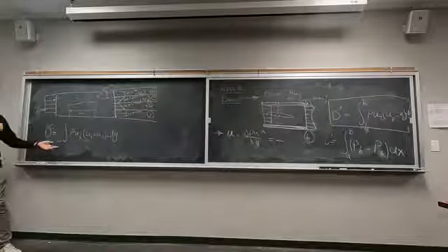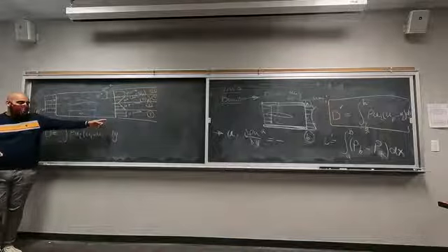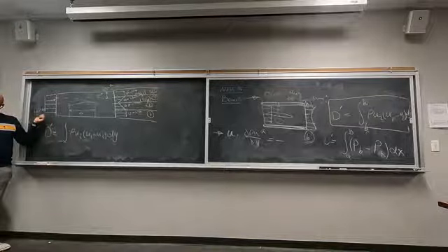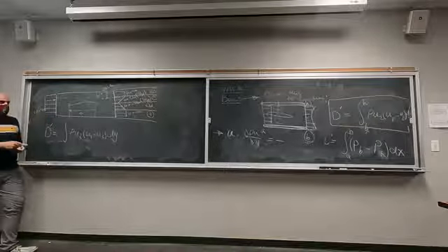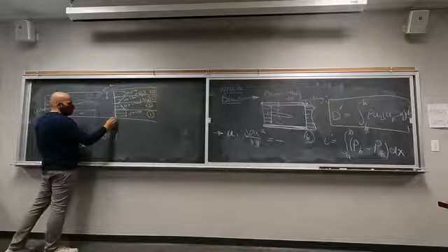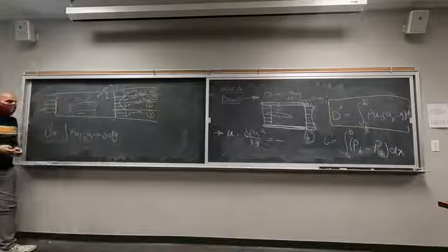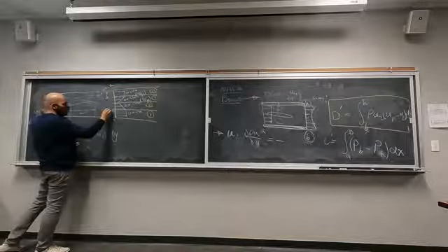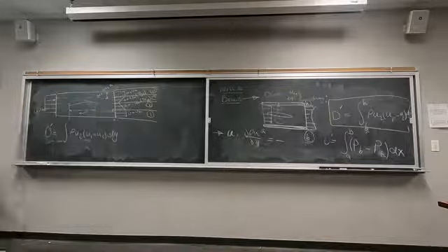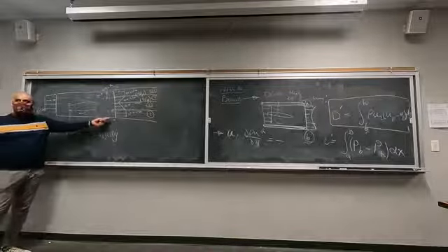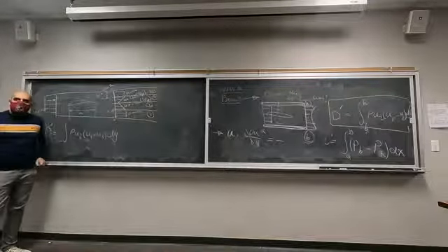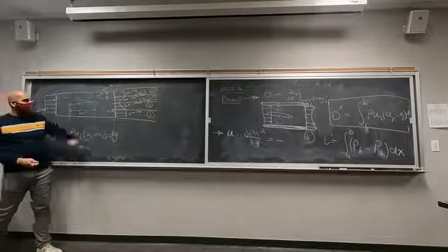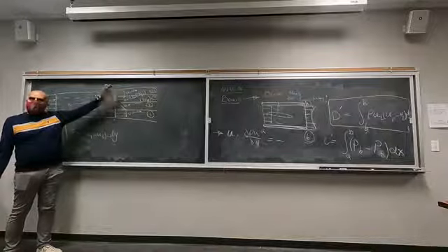What will be the solution of this integral in region 1? U2 is equal to u infinity. U1 is also equal to u infinity. So let's say this is the integral from 0 to 0.25, that's 25% of your chord length. Let's say your chord length is 1. What will be the solution to this integral? 0, right? U1 and U2 are equal. What about region 4? 0 again, u infinity.